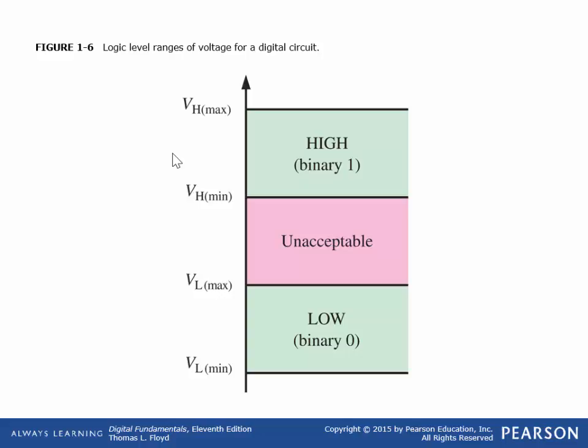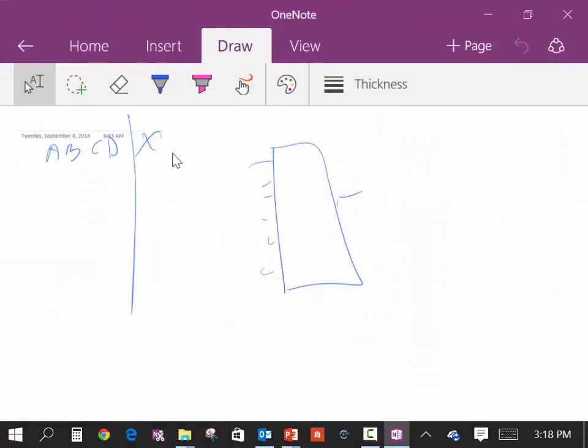There's the linear range, and then there's saturation, where you've got full current and it can't go any further. When you study analog amplifiers, your goal is to always stay in the linear range, because if you exceed the linear range, you get distortion.